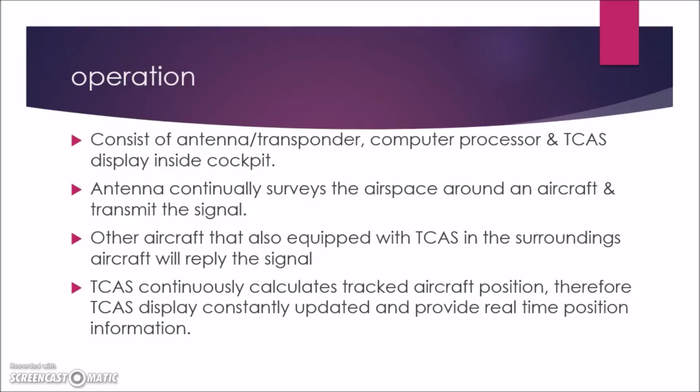The power is less than from ground radar, but sufficient to trigger a response from aircraft that may be less than a minute of flight away. The distance to the aircraft is determined from the timing of the signal. Closure rate is derived from two consecutive measurements of distance, and pressure altitude is part of the transponder response.